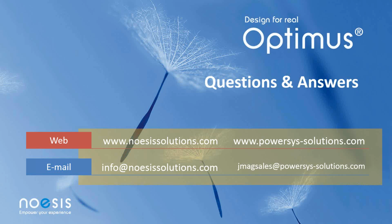You spend a lot of time talking about response surface modeling, but how do I ensure that I have a quality RSM? Optimus has a number of built-in measurement tools. When it comes to modeling or approximating a surface, typically you have a value called the R-squared value. Optimus reports that data for all of the response surfaces.